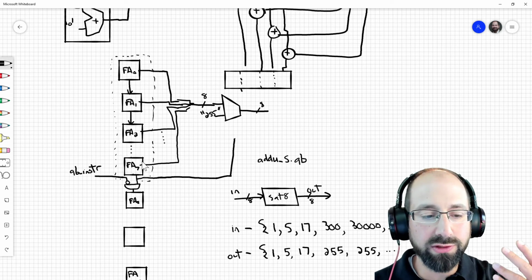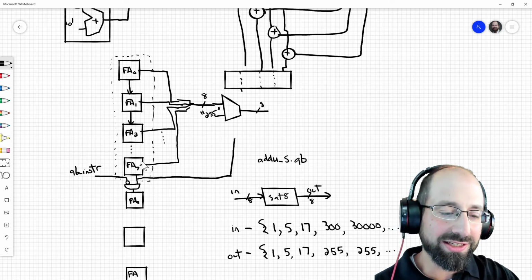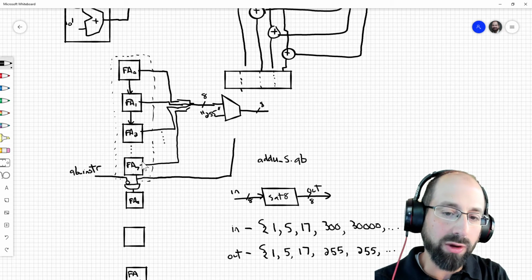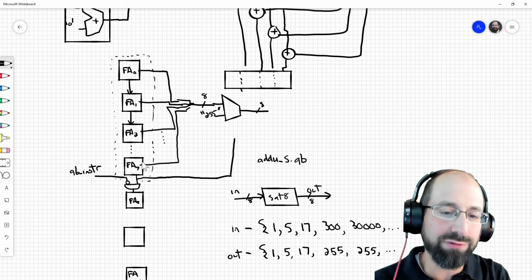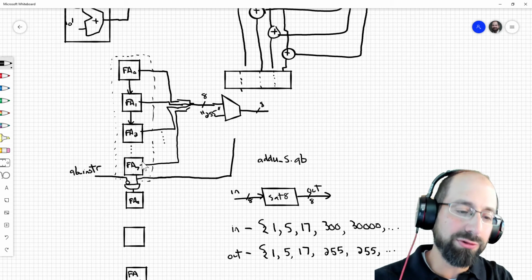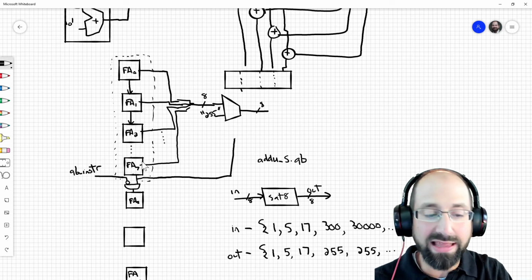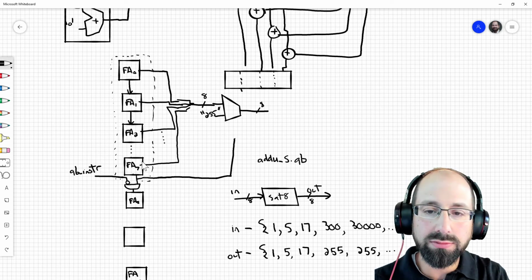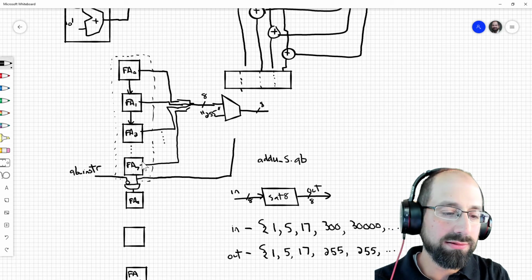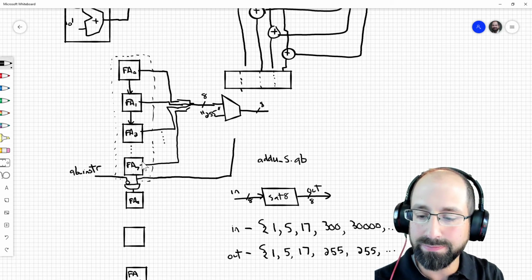I like to think of it in terms of translating maybe human spoken logic to the circuit elements we understand well. So the mux is one way to represent a complex if condition. If something is true, then take this. Otherwise, take this, right? So that's always a mux. But if we need multiple things to be true, what would we want to add? Multiple things have to be true for us to take that second input, not just one thing being true.